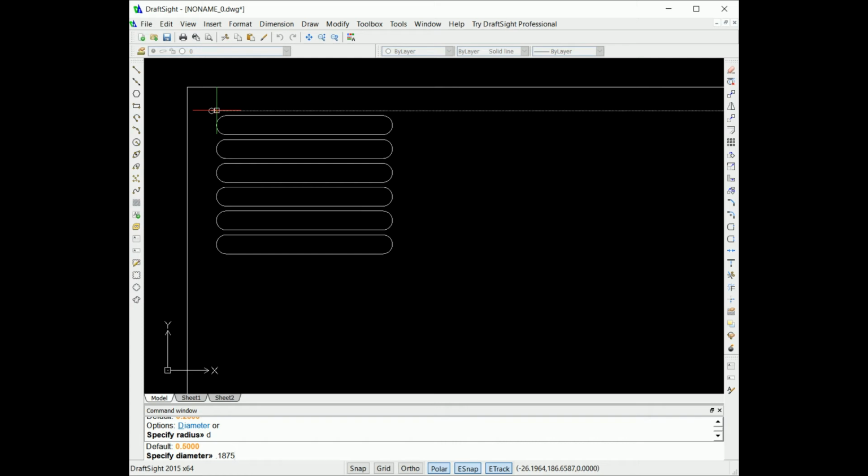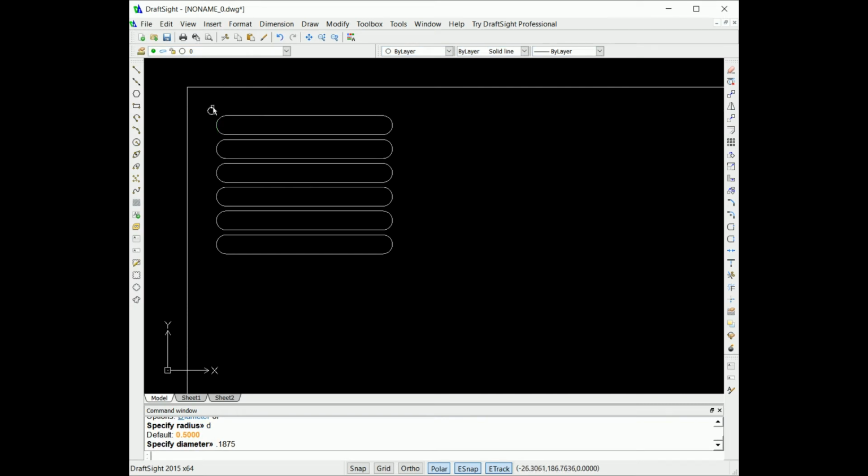Now, I'm going to hit enter, and we're done. Our 3/16 hole is up here, and for American screw gauge, that would be a number 10 screw for a 3/16 hole. That gives you a little clearance for a number 10.